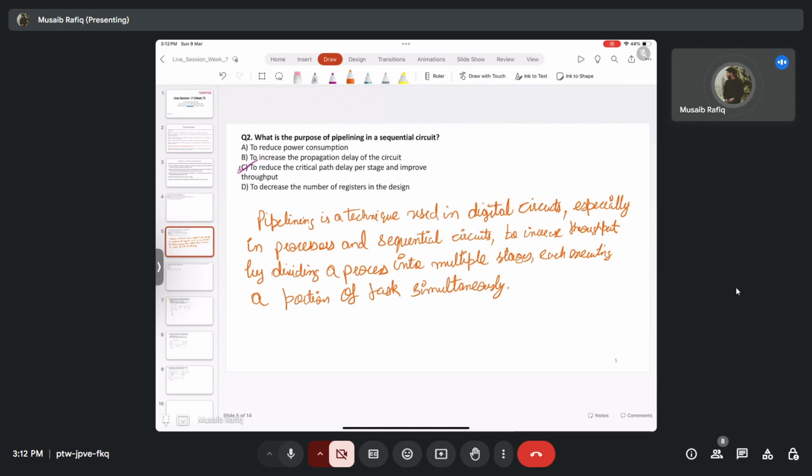So as a result, let's say a particular block A takes only 2 units, and another block takes 4 units, so for 2 units of time block A remains idle. What we mean by pipelining is we introduce registers, the memory elements, after each of these blocks, such that once logic block A performs computation, it doesn't remain idle. The next set of inputs comes and it performs computation on that. And in the meantime, other blocks are performing their computations in parallel.